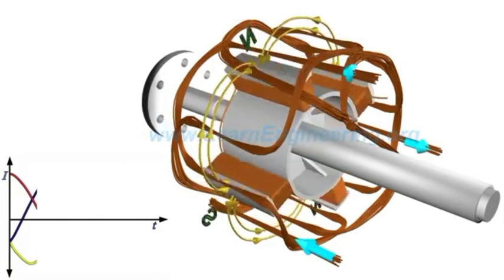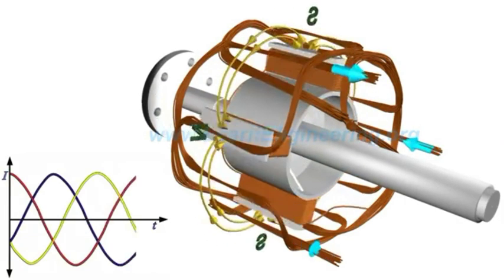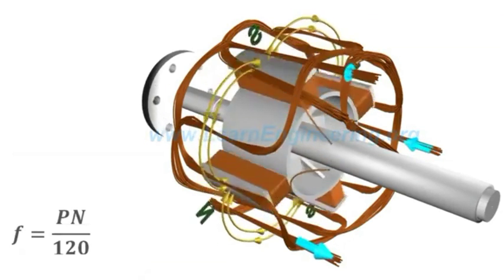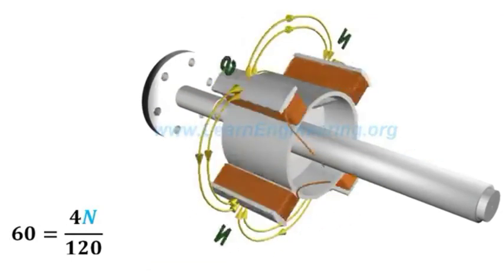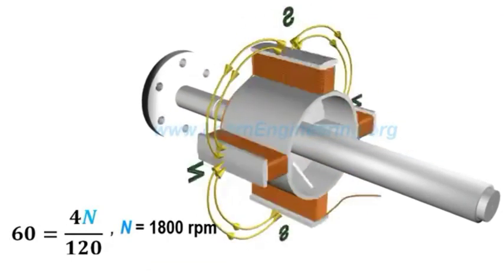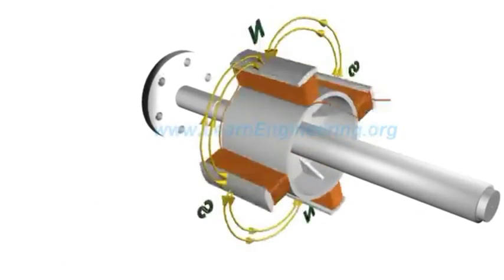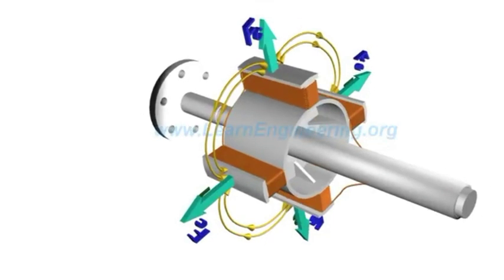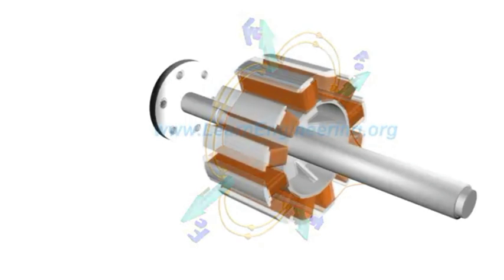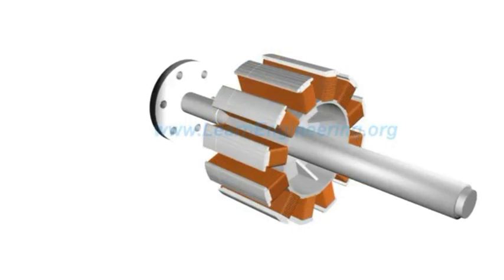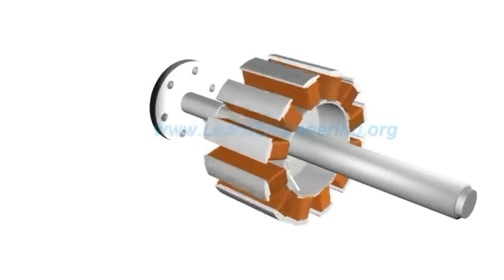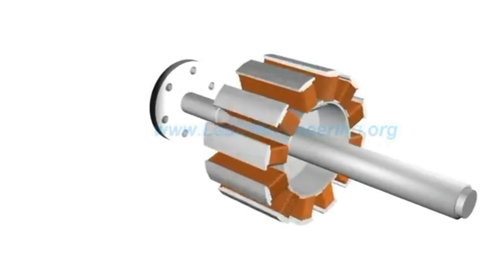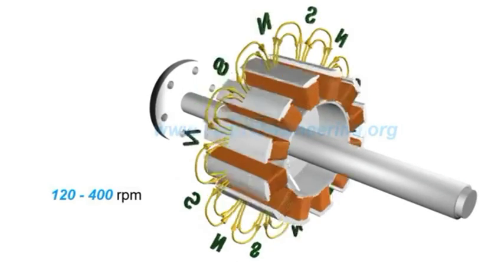It is clear from this equation that in order to produce 60 Hz electricity, a 4-pole rotor should run at the following RPM. Such huge RPM will induce a tremendous centrifugal force on poles of the rotor, and it may fail mechanically over time. So salient pole rotors generally have 10 to 20 poles, which demands lower RPM. Or salient pole rotors are used when the prime mover rotates at relatively lower RPM.